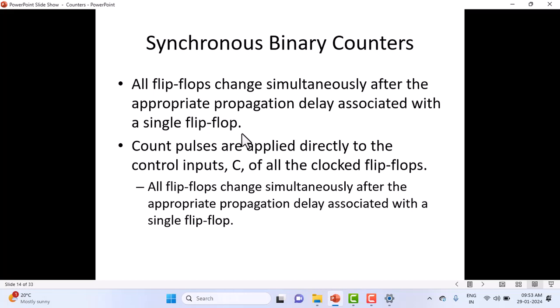Each block requires different frequency. That's called clock tree synthesis. You must use source clock and divide that clock into the requirement of individual blocks. One block may run at 0.5 gigahertz, another block may run at 10 megahertz, or there are blocks which can run at few kilohertz also. The objective of clock tree synthesis is you must identify what is the clock requirement for each and every block, and design proper circuitry for that so that clock distribution is done without affecting the overall system performance.